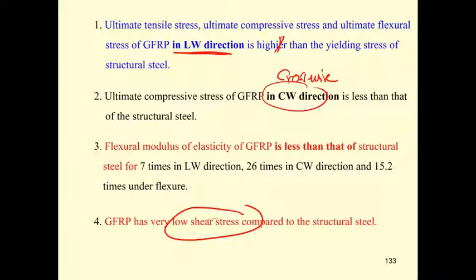So you don't need much care for the design of the maximum moment. But in the design, you've got to take good care of the Vmax, the maximum shear. Also the maximum deflection. It's going to be okay for the M, but it's going to be very, very susceptible for these two in the design.